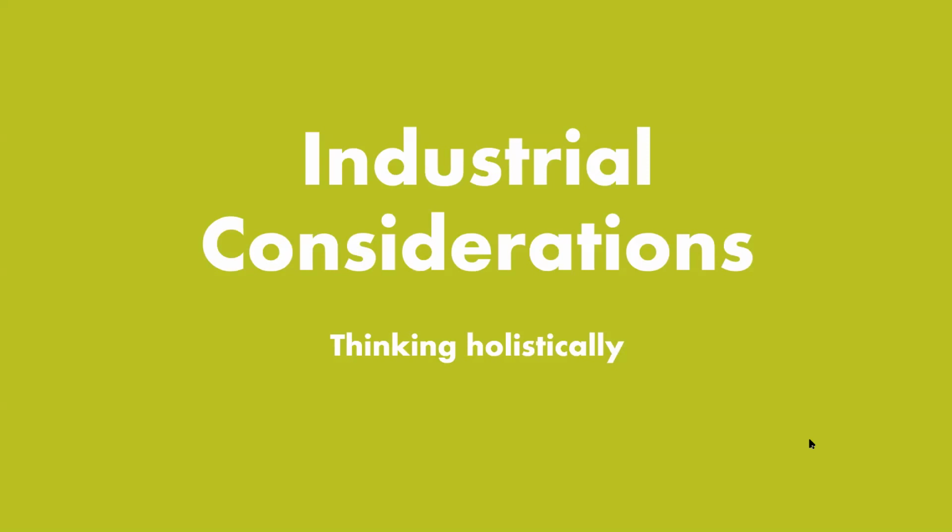One thing I want to circle back to is what Kelsey said very early on in the presentation, and that is a lot of people ask, what % fill do I need for my application? And I just want to reiterate that once we have a problem definition and an understanding of the problem objective, the first step for us is going to be to determine the media volume. So generally, we design the reactor around the media volume. That's how we approach greenfield designs. It's also how we approach existing systems and retrofits.